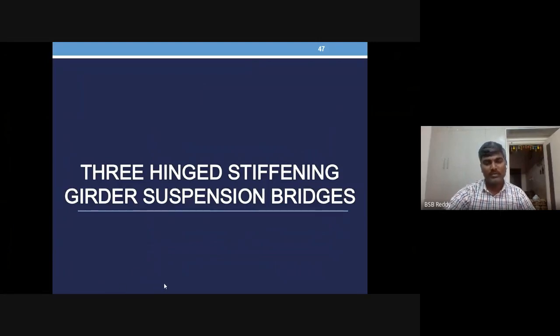It is an element placed between the two piers which carries the load from the pathway or carriageway. Vehicular load, the movement of vehicles, causes moving loads as well as dead loads from the carriageway. The carriageway has to rest on the girders, and in turn, girders transfer the load to the piers.